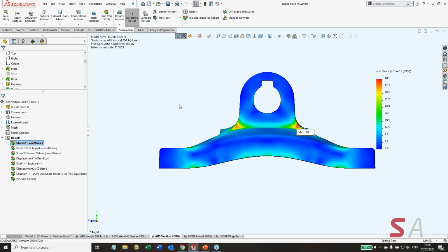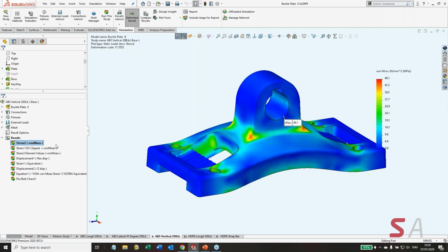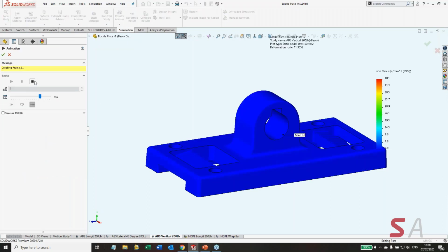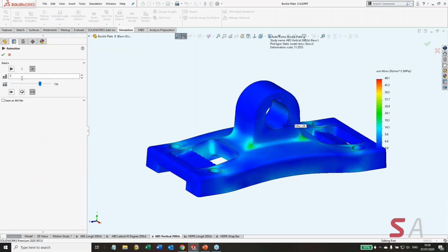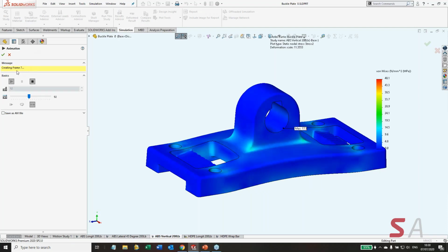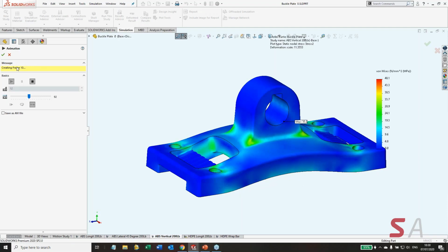One of the things that I like to do when I'm not sure about something is I will animate my study off of a right click. And when I animate it, first thing I'll do every time is stop it and put more than the default 5 frames in there. I'll usually go between 10 and 15 frames, and I'll slow it down to something under 100. That's just a number for the speed. I've discovered somewhere around the 60 to 80 to 90 is a reasonable range. And what it'll do then, it'll make up a dozen frames first, and then it will start oscillating it slowly.